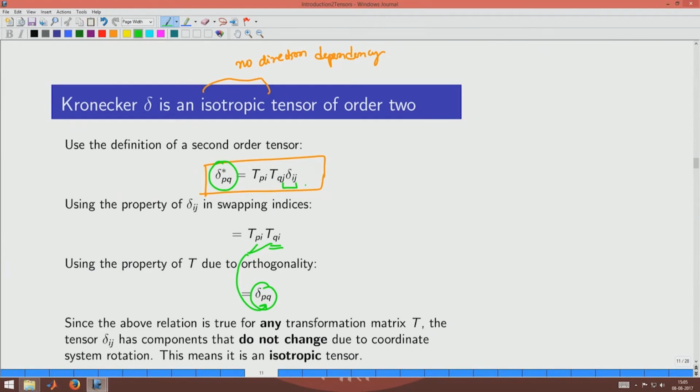And we use the Kronecker delta conveniently to represent any property that is an isotropic property. So, we pick a quantity and use delta before it and say that this could be my property as I want. I use this kind of expression whenever we want to represent a property which is a second order tensor, but an isotropic one. So, this is how we make use of the isotropic tensor given by the Kronecker delta.